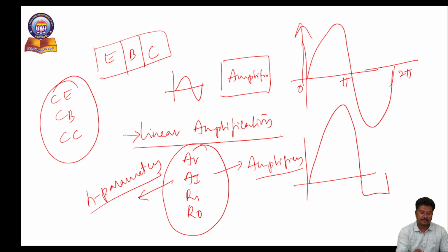That's why first we have to consider the transistor as a two-port network. Unless we consider the transistor as a two-port network, and make the transistor equivalent to an electrical component, it is not possible to know how to find the H parameters. Why? Because H parameters are very crucial in order to find all the parameters of the amplifier. That is the reason we first consider the transistor as equivalent to a two-port network. So the first condition I am considering: the transistor is a two-port network.